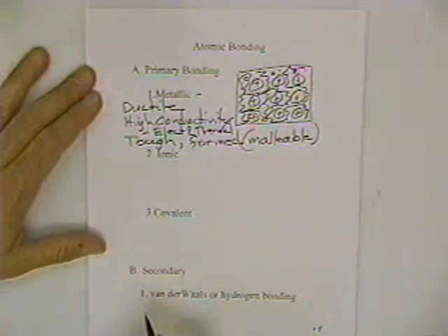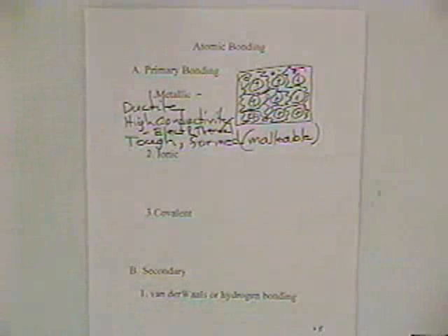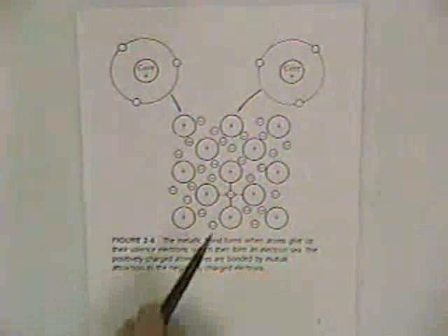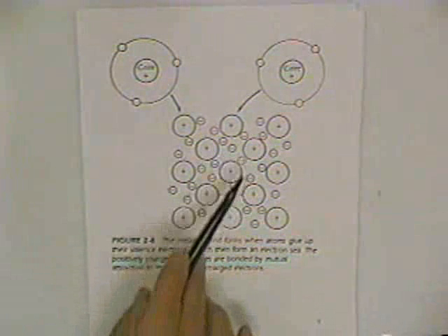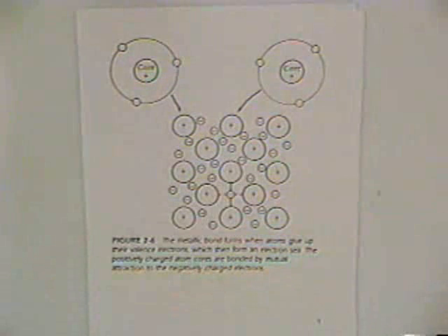Now, a downside of the metallic structure is that most metals would rather be oxides. So it is relatively easy for corrosion to occur, and so we work hard to protect metals from the environment. There is a picture of metallic bonding on page 9 of the notes, and it suggests the little picture that I showed you a minute ago, where you have cores with electrons. On average, if it's a univalent or single valent material, one electron will be associated with each ion, each positive core.